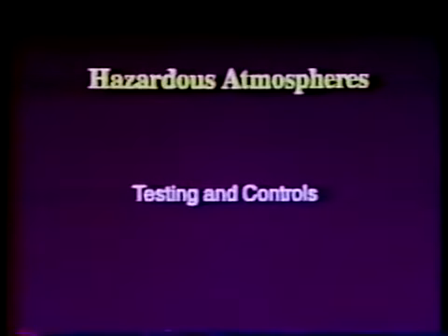When mobile equipment is operated next to an excavation or when it must approach the edge of an excavation and the operator does not have a clear, direct view of the edge, a warning system must be used. This system may involve barricades, stop logs, or signals. To prevent exposure to harmful levels of air contaminants and to assure acceptable atmospheric conditions, certain requirements must be met.